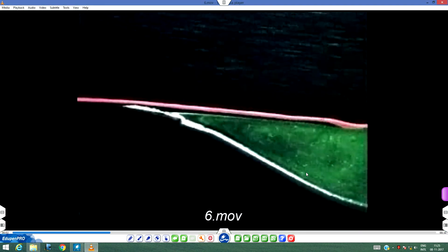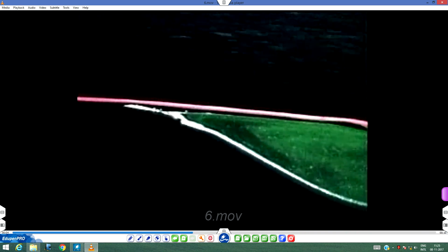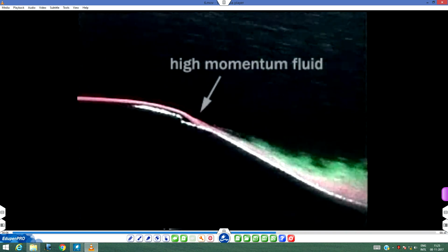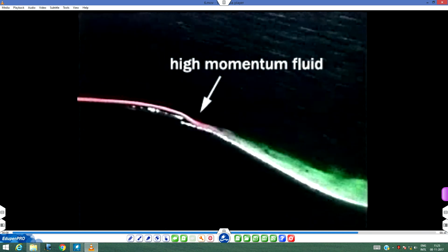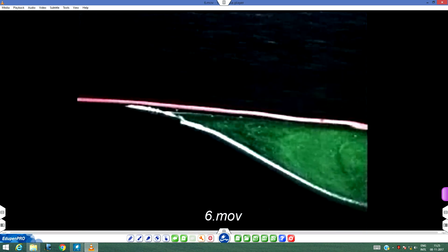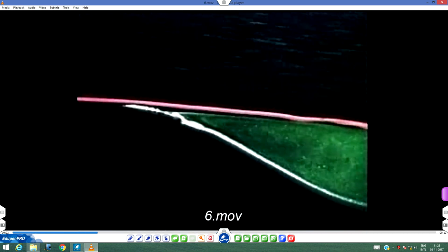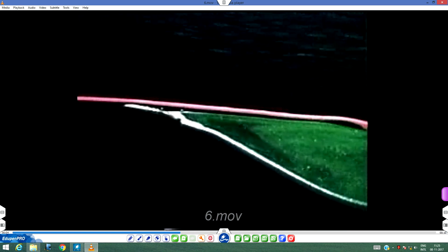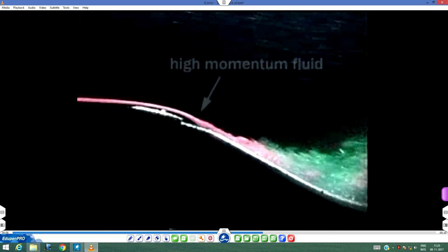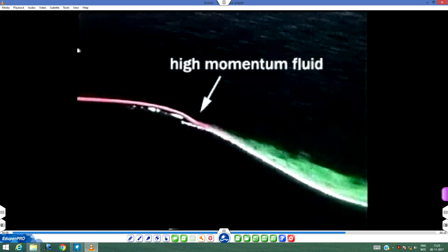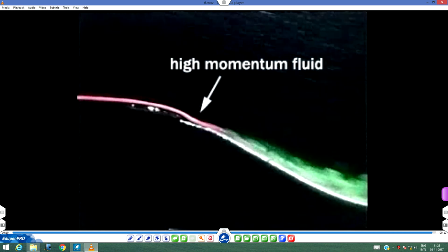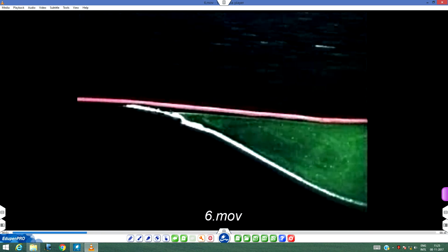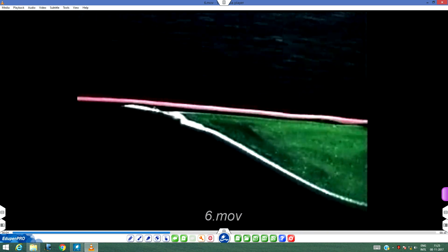This one, yeah, has that momentum injection. Yeah, you can see that boundary layer was separating, and then with a little bit of injection of fluid from the wall, suddenly it attaches to the wall. That is a delay in the point of separation, and hence a reduction in the wake size, reduction in the drag coefficient.